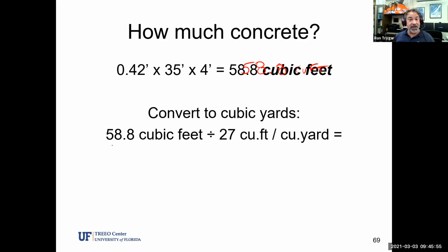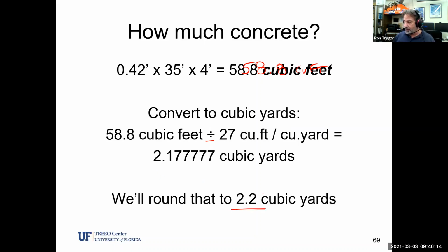Now we need to convert that into cubic yards. So 58.8 cubic feet divide by 27. And now for cubic yards, I have 2.1777777. And I would say, you would probably round that just to 2.2 cubic yards. And that's all we would need.